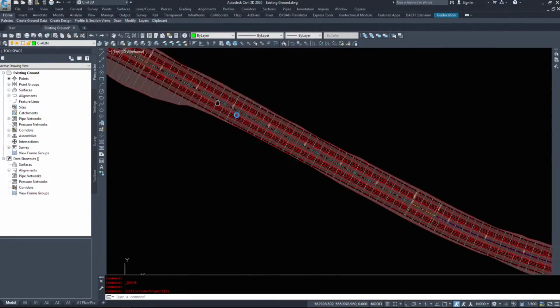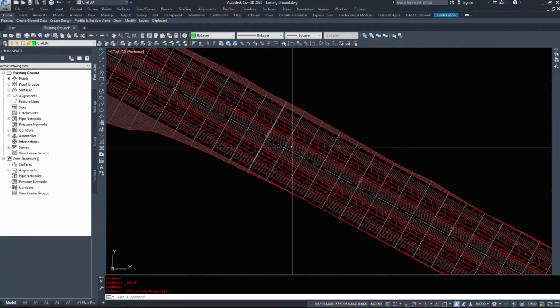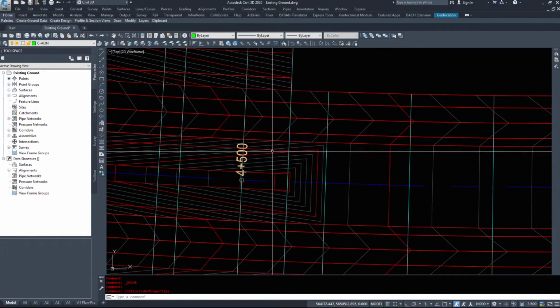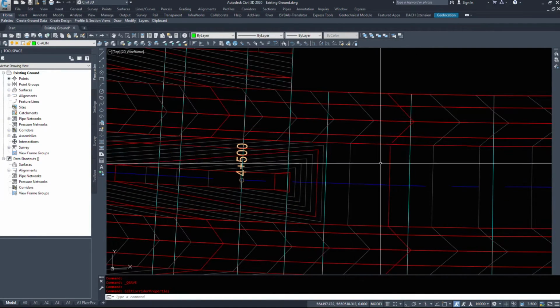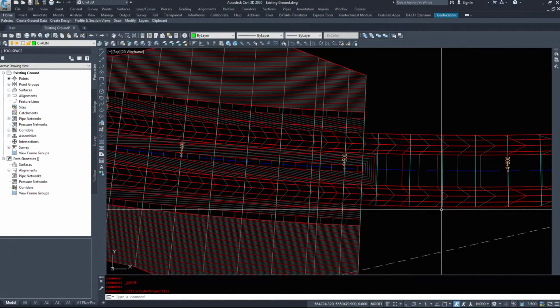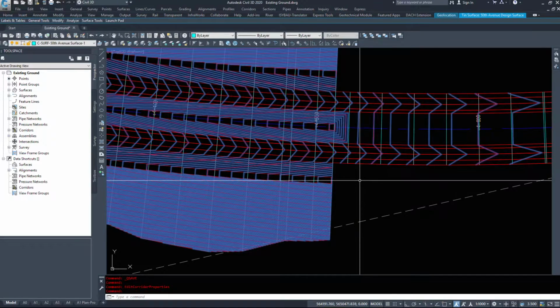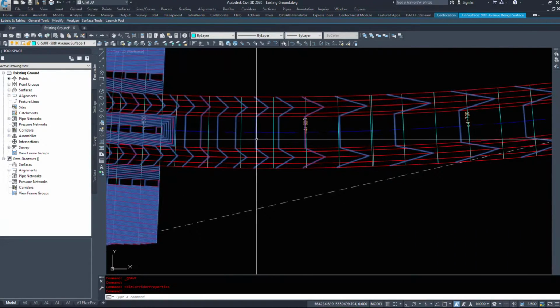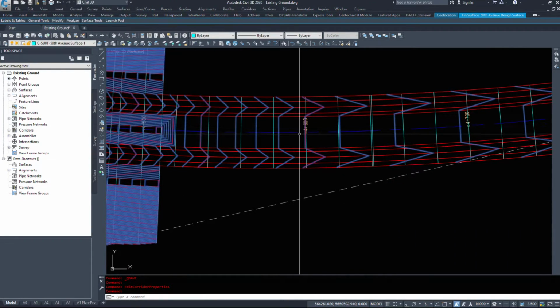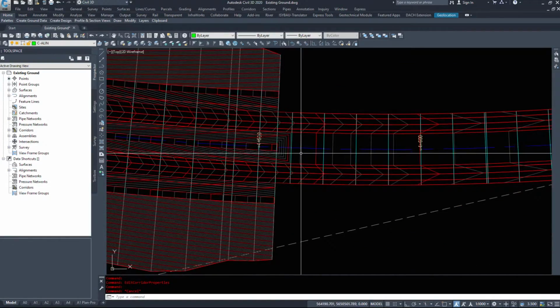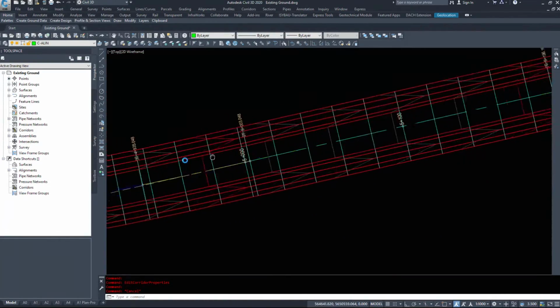And when we get to our bridge section, if I can find it here, right there, our contours should keep the same general shape. We don't have a drop. We don't have any weird bumps, except the center here now targets just smooth and flat. But again, we can remove that with just some triangle editing. Our ditch ends here, but that's not a big deal.